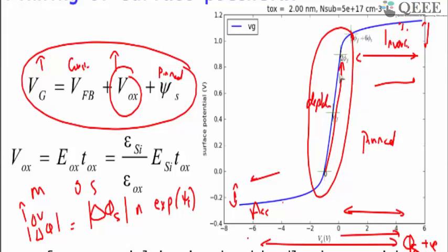Okay, by solving that equation only, we are getting this one. So this plot is by solving the full Poisson equation, taking electrons and the whole contribution into account. What we did now, the symbol, is solving the Poisson equation by assuming depletion. That is why you can see this kind of a linear or sublinear relationship here.